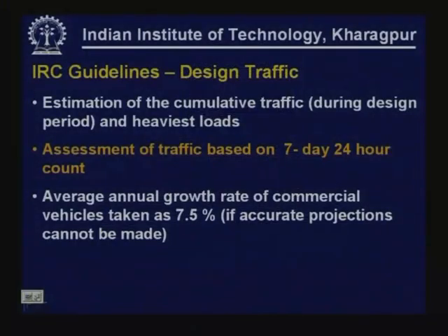The estimation of cumulative traffic during the design period and the heaviest load has to be made. This is how we consider the design traffic. We are interested in the total number of repetitions of commercial vehicles, the loads that are going to be carried by them, and the heaviest loads that are going to be applied. So, we have to have an assessment of the total traffic volume and also the heaviest loads.